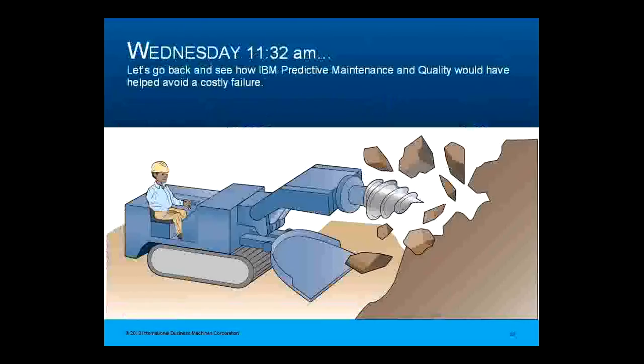But as in any environment, it's not just relevant or important to have a model that predicts a failure. You also have to have an actionable result. And here, in this example, the operators know that they could perform a simple flush procedure that would require minimal downtime. This flush procedure cools and softens the seal, and by knowing which of the fluids the machine is running and the age of the seal, the predictive model can tell us exactly when this flush procedure would be helpful.